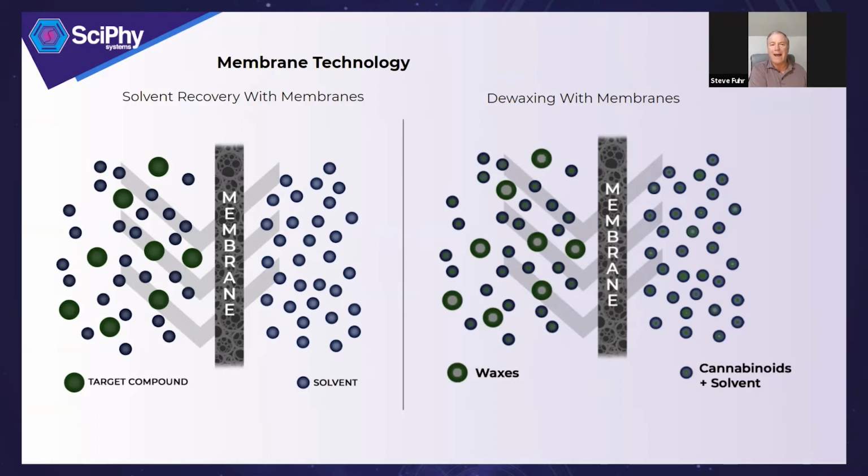You're not removing one batch and maybe manhandling a batch over to another station. These membrane systems are actually able to hook up directly to the extractor. So that touches on another key contributor to cost, which is the labor side. This is going to save energy because you don't have to do the big temperature swings. You're just using pressure to achieve the separation, but it also enables a continuous flow-through type operation. And continuous flow-through operations typically are going to let you bring your labor down.